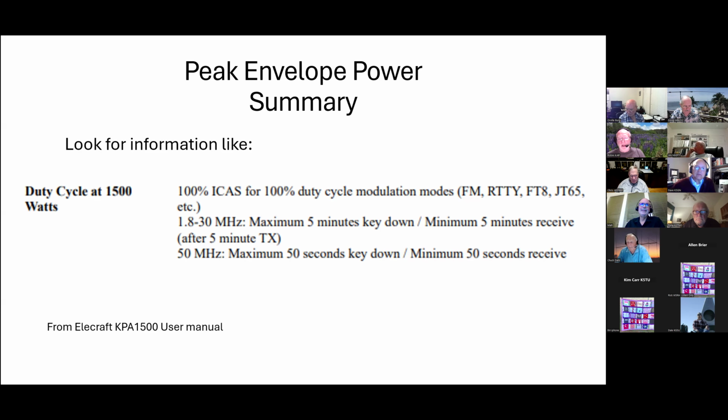And the thing we're talking about here, these are continuous voltages. Whenever you look at the capacitive reactance and inductive reactance in these circuits, the transient voltages are likely higher. Those are things you will never see except for one cycle, but that's all it's going to take to cause your tube to fire over, too. Yeah, right. Lots of interesting things. So you want some headroom.